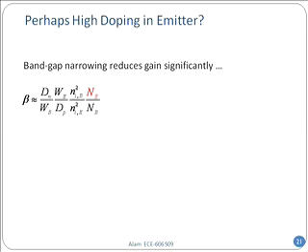First of all, when you have high doping, do you remember band gap narrowing? I talked about these band tail states coming in when you dope very much. So that is one problem that will effectively make this Ni squared much smaller than Nib squared. I have a typo over there, I'll fix it on the numerator. So that's one problem. But the more important problem is,